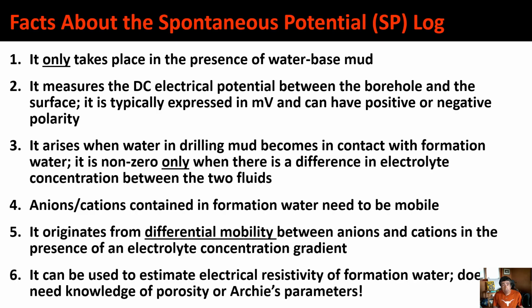Now, what are the facts? Here are some of the facts. It can only take place in the presence of water-based mud. No way that it will take place in oil-based muds. Why? Because we need to have electrolyte concentration in the mud, and oil-based mud does not allow electrolyte concentration.